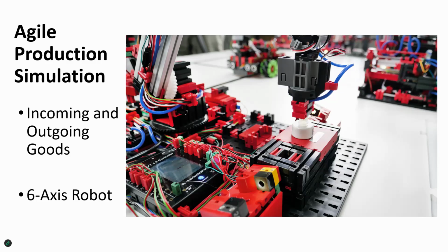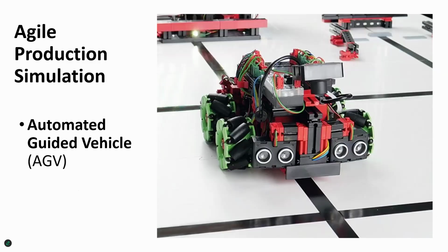In this station, the raw material is delivered at the goods receipt slot, positioned on the color sensor for quality control using the 6-axis robotic arm with a vacuum gripper, and it's then encoded on the NFC reader. The 6-axis robot then places the workpiece on the automated guided vehicle, or AGV, for further transport. You, of course, see the model here. This module also contains the central control unit, which is a Raspberry Pi, and the environmental sensor, which measures the different environmental conditions in the factory.